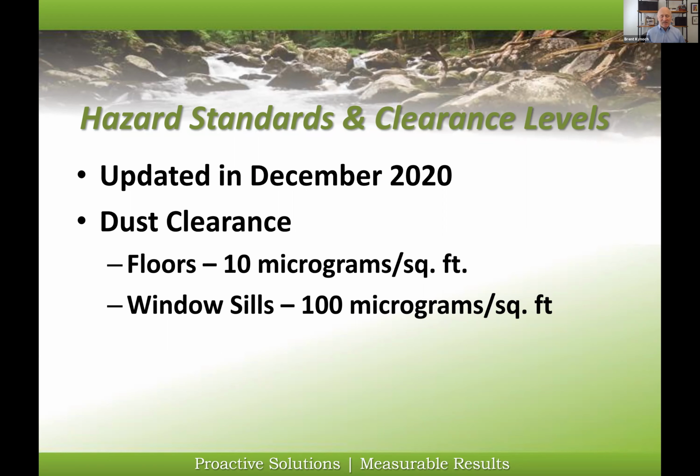What the CDC has said is there is no known safe level of exposure to lead or lead dust, so they've lowered these levels. You'll find that both Maryland and DC have adopted these levels in their clearance requirements as well. So if I'm in a facility, unit, or house testing to see if there is any lead-based paint hazard, I've got to meet these levels, and after an abatement or cleanup activity, I've got to meet these levels as well.